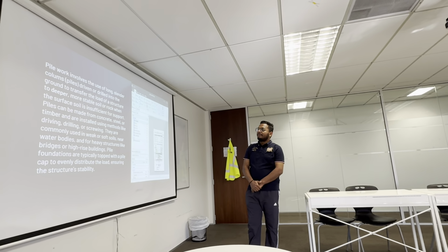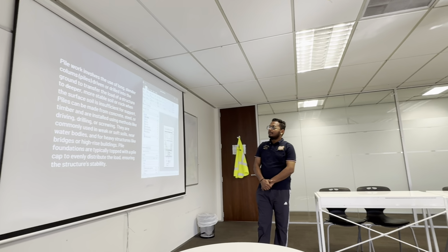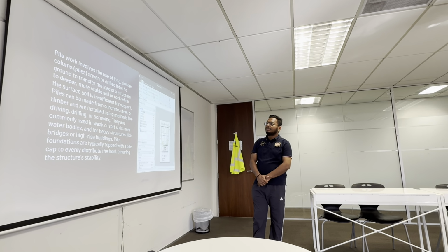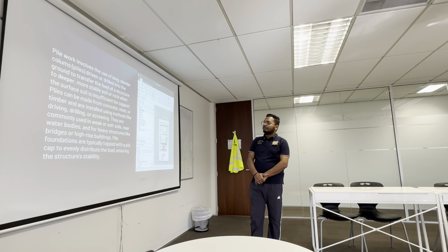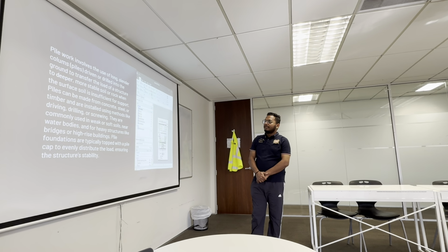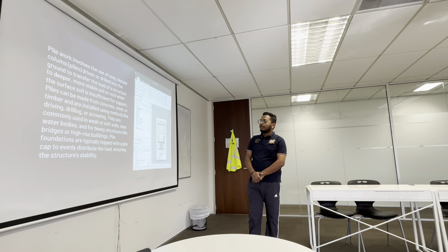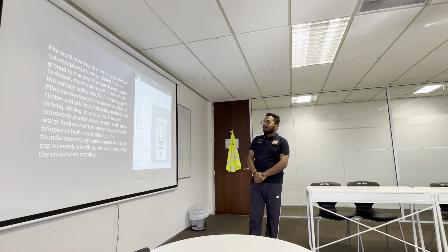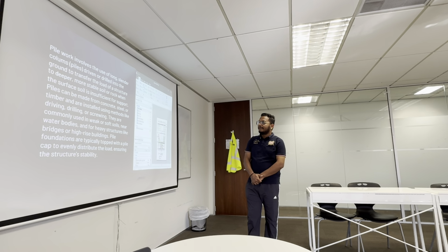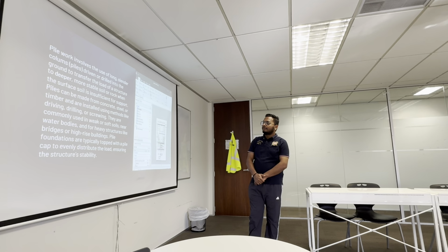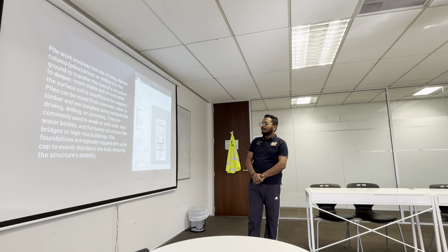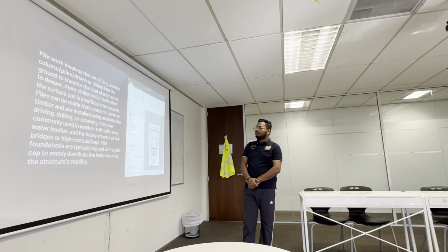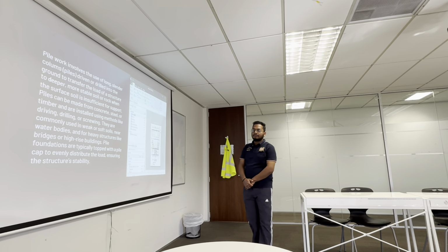Piles can be made from concrete, steel or timber and are installed using methods like driving, drilling or screwing. They are commonly used in weak or soft soil near water bodies for heavy structures like bridges or high-rise buildings. Pile foundations are typically topped with a pile cap to evenly distribute the load, ensuring structural stability.